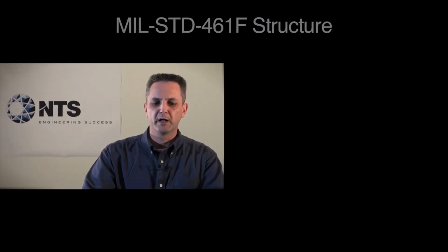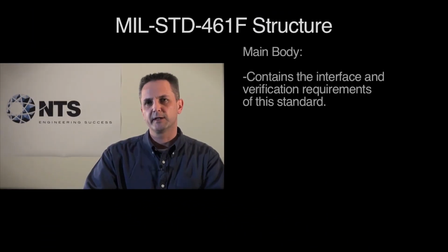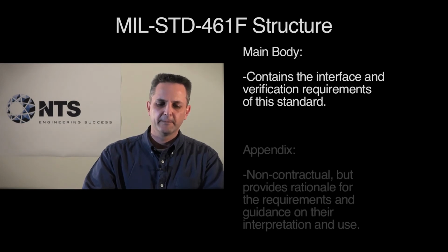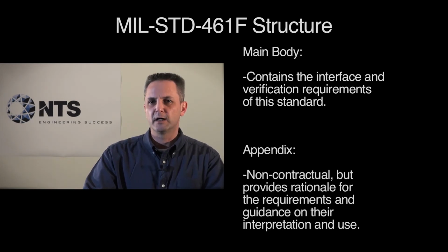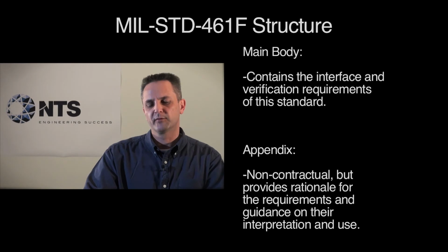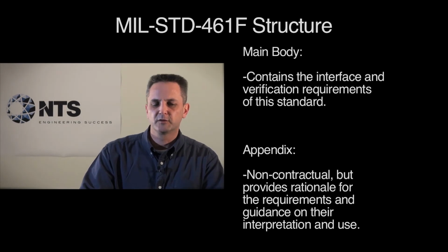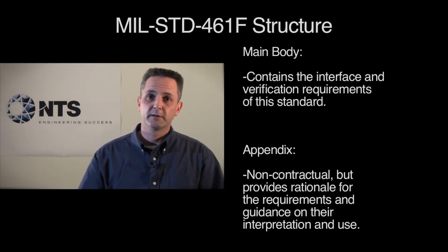Now, the standard is structured in 2 major parts. The main body, which contains the interface and verification requirements, and then the appendix. The appendix is a non-contractual portion of the standard, but provides rationale, lessons learned, details of the requirements, and guidance on the interpretation and use of MIL Standard 461F.